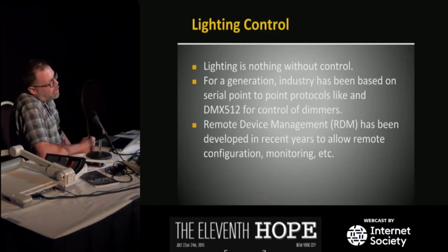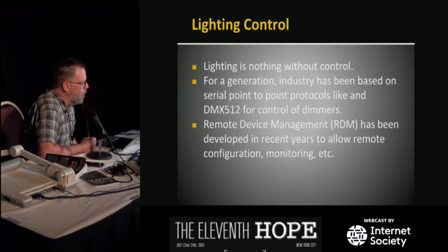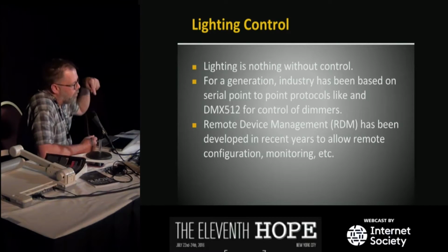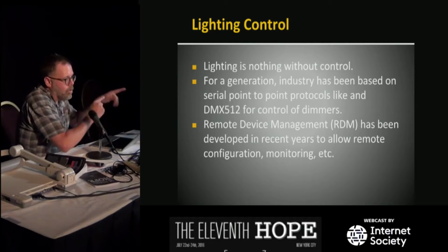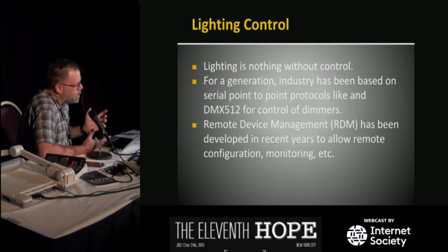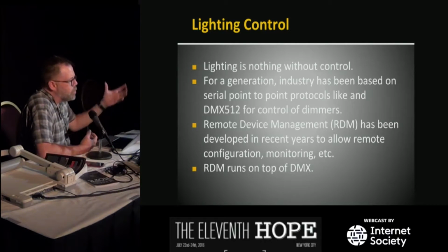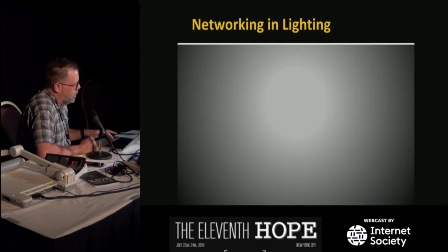Also in the last about 10 years, there's another protocol called remote device management that's been coming around. It rides in the back of DMX, and allows you, for example, if we had a moving light over here, to set some parameters in the moving light without having to get a ladder out and push some buttons on the back. Also, we can monitor lamp hours and things like that. So that's finally starting to catch on a little bit. That's a long story, but it runs on top of DMX. So that's where we were prior to networks, although RDM's sort of after that. The timeline's a little bit simplified here.